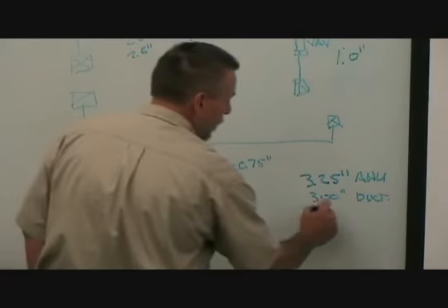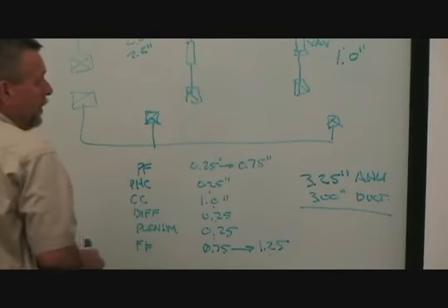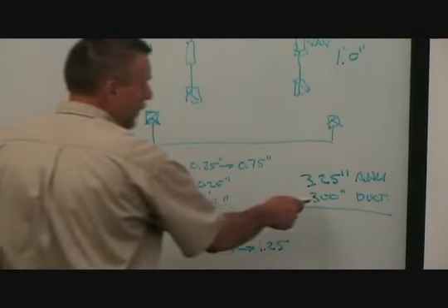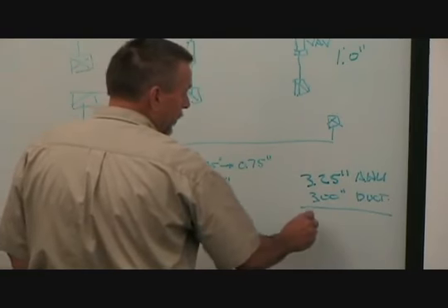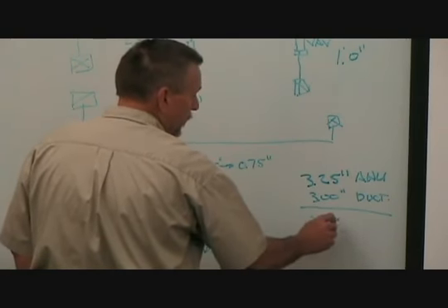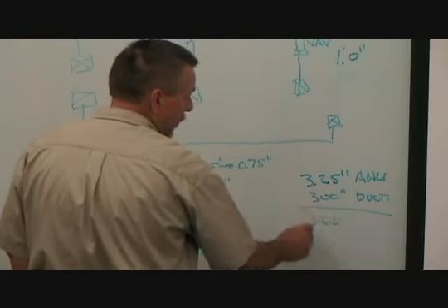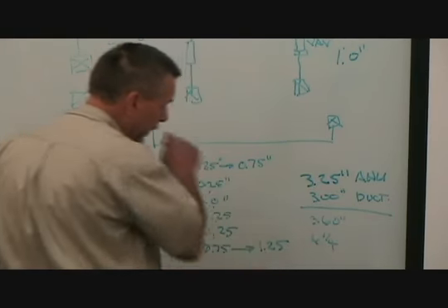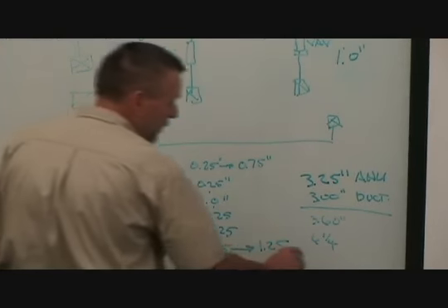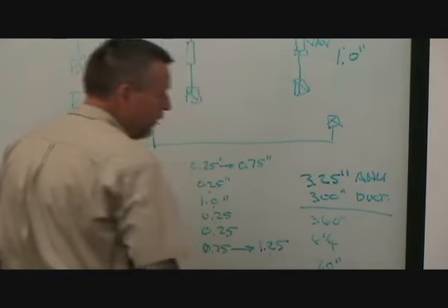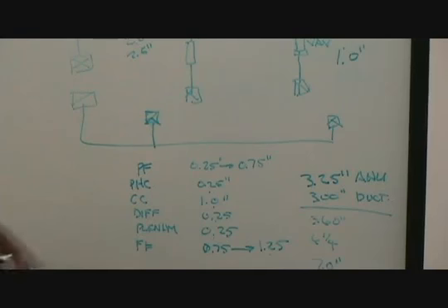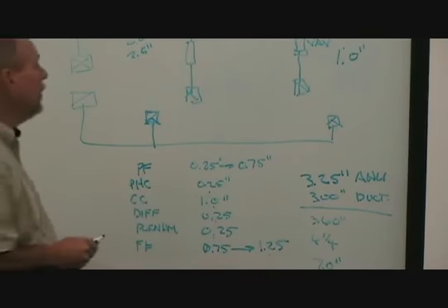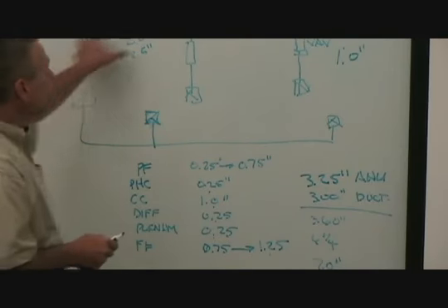So again, if I'm concerned about the ductwork and the fittings, that's not the entire pressure drop. If I increase this 20%, that just gets me up to 3.6 inches. And so my total is going to be somewhere around 7, 6 1/4. The engineer is going to put some safety factor on there, probably even selected at 7 inches for some safety factor, including this safety factor right here. That's not actually a safety factor, that's a fairly known system. So it calculates very similar.